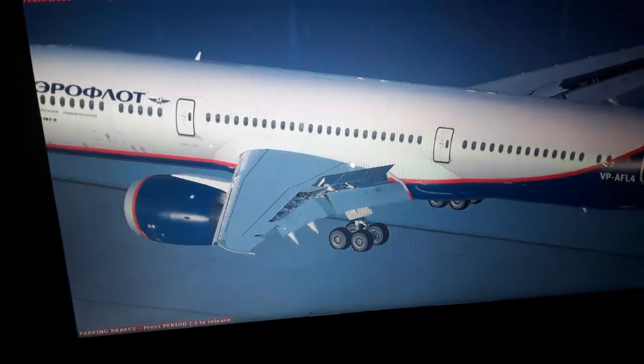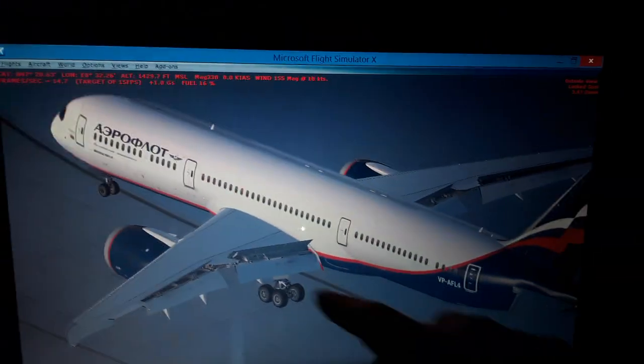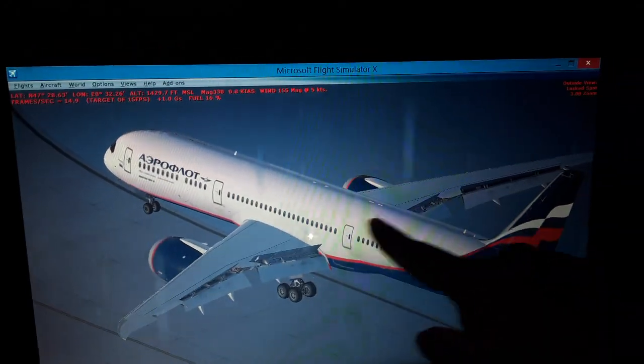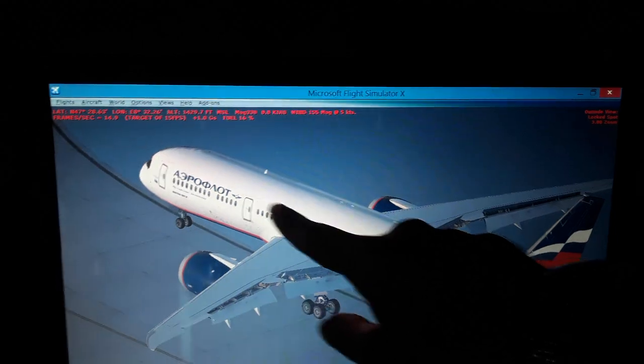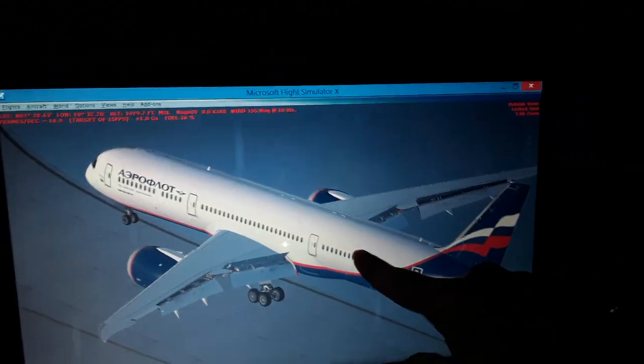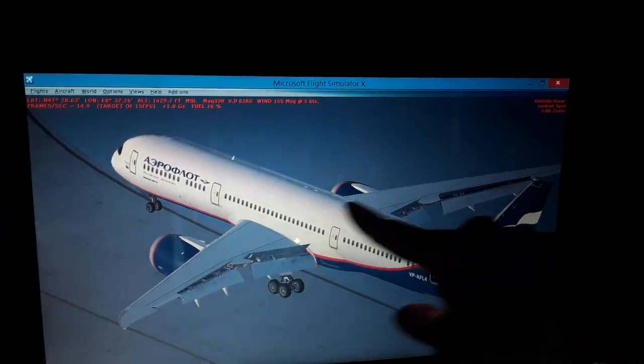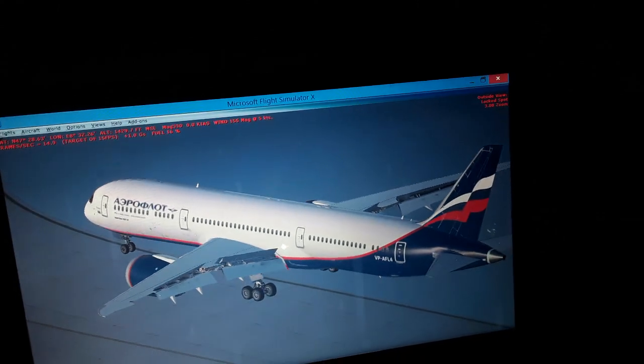We also have wing and engine anti-ice. We have pressurization from the engines coming in for the hydraulic fluid tanks pressurization, cabin pressurization, and oxygen systems. The wing and engine anti-ice is over here also, from the manifolds.